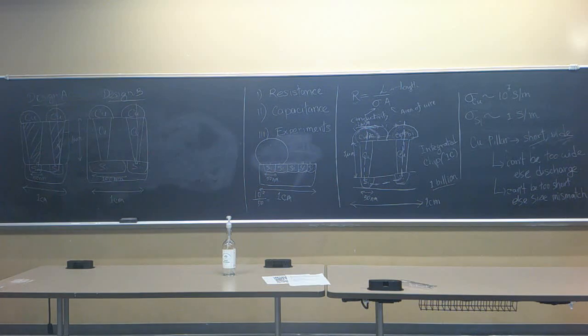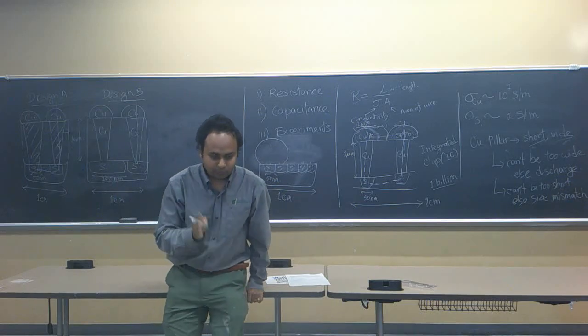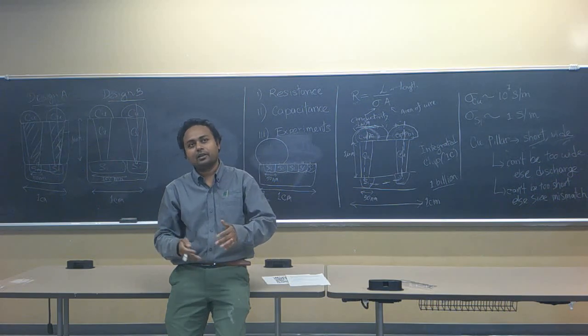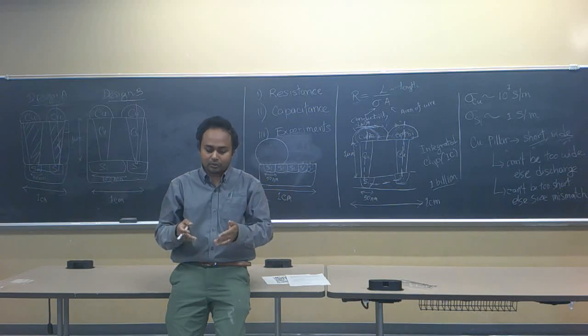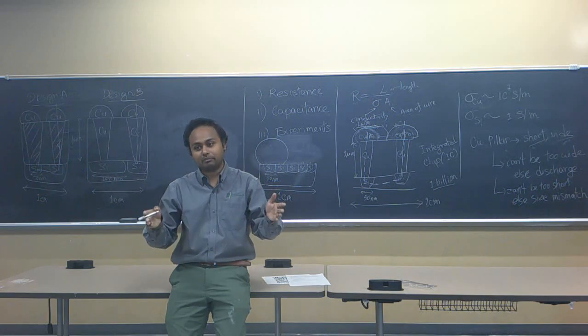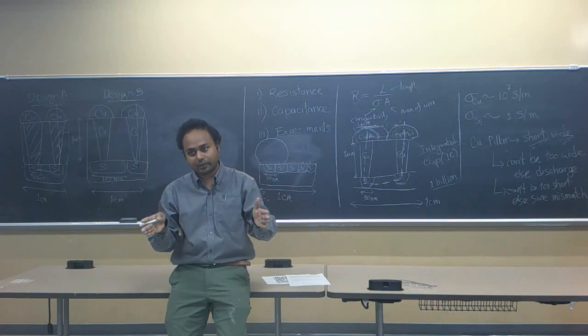So at one point of time, the process node actually corresponded to the physical size. For instance, long time back when we started designing ICs, we said it's a 1 micron node. So 1 micron really meant that it's a 1 micron device. The silicon device itself is 1 micron.